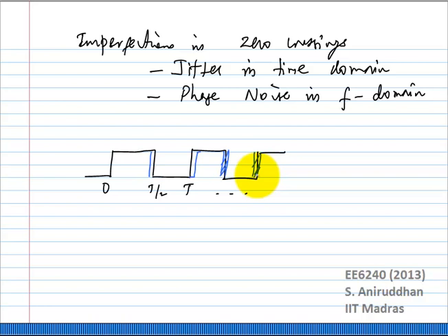We have seen cases like this before. For example, in the mixer, right, the differential pair noise actually changed the switching instant. Okay, we expect something similar to be at play here. Noise from the devices actually changes your ideal zero crossing. Okay. So at every zero crossing you have this problem. Okay. How do you characterize this? So maybe you have delta T2, delta T1, delta T3, delta T4, and so on.